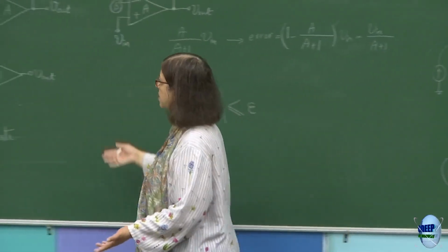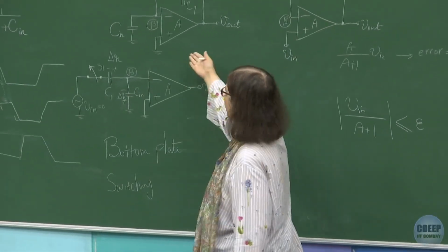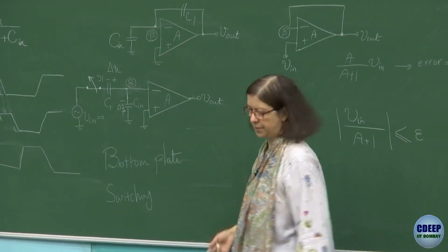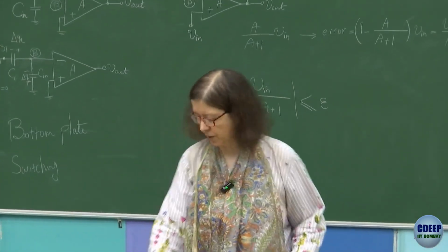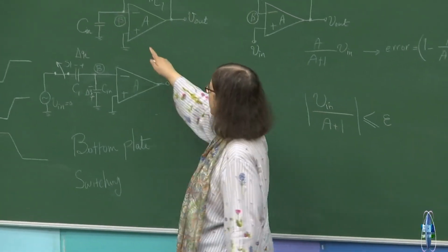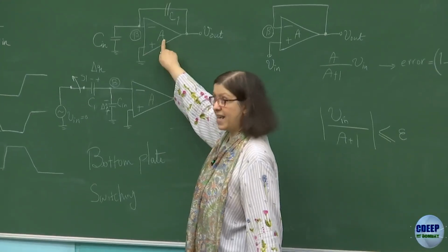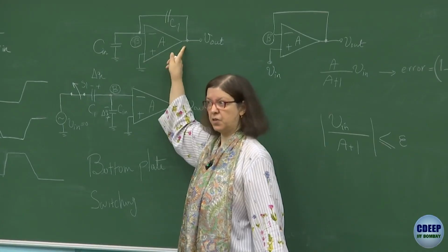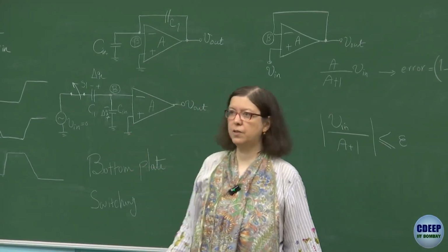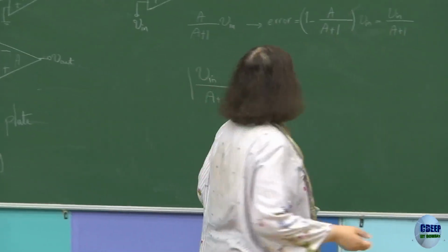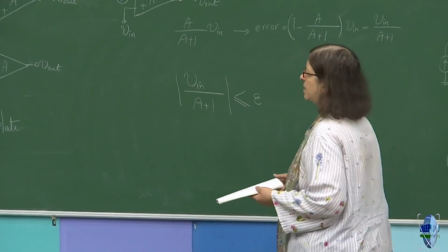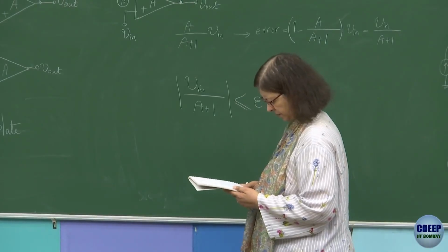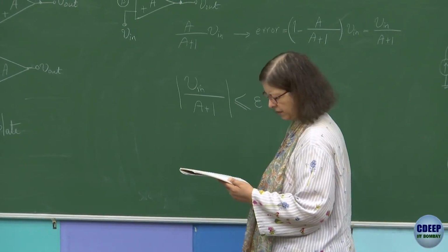So the same goes here. In fact, you have this circuit now. Therefore, don't consider B as ground and actually analyze it. Same thing, eventually you consider you have a voltage VB over here, then VB multiplied by A will give you Vout, and VB itself is the capacitive division of Vout. You will get Vout as a function of Vin. And Vin is the voltage stored on the C1.